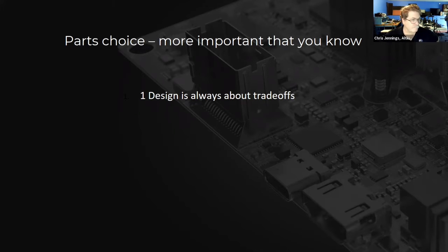And that takes a lot more work. It also means that you have to be more careful in the PCB fabrication. It requires having a controlled impedance. If you don't have the right impedance, then you're going to get reflections, you're going to get EMI, you're going to get reduced performance, reduced distance, and maybe it might not work at all, depending on how bad it is.